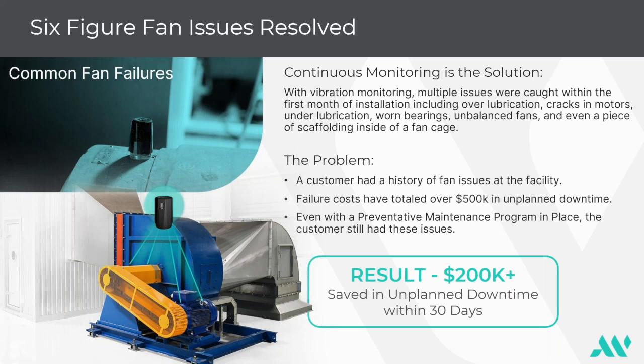So long story short, with multiple fans we found imbalance, looseness, cracked motor feet, and even found scaffolding inside the plenum of the fan. That was kind of a huge find for us, but that was just one of the issues. The result was over $200,000 saved in unplanned downtime. So that was a big win.